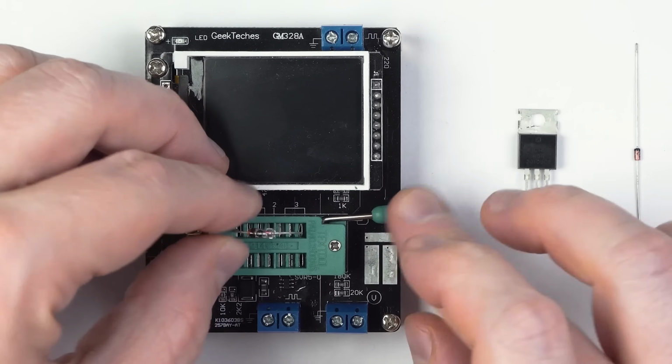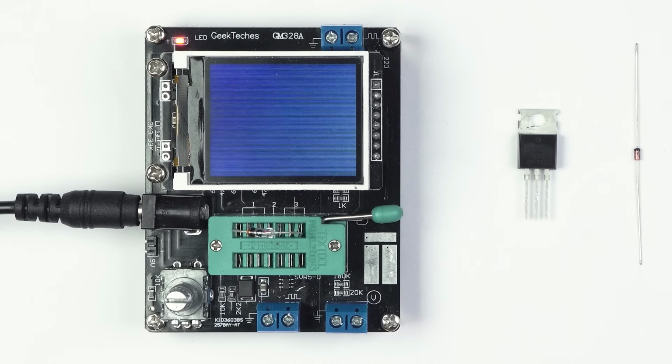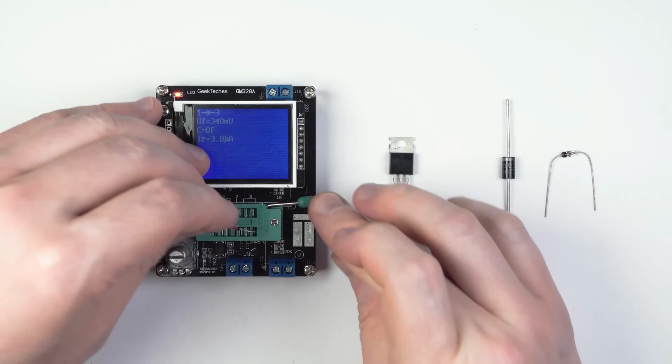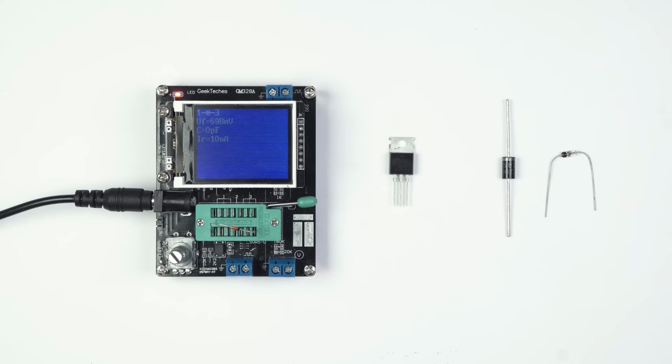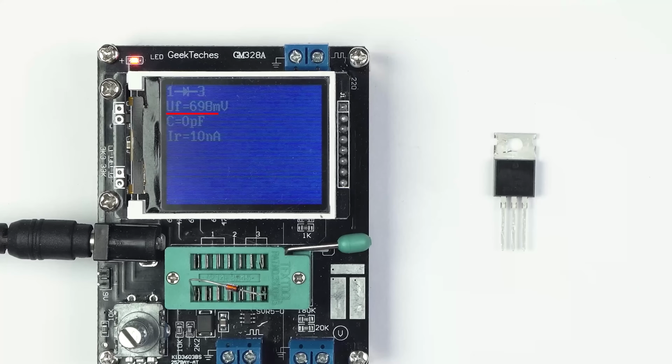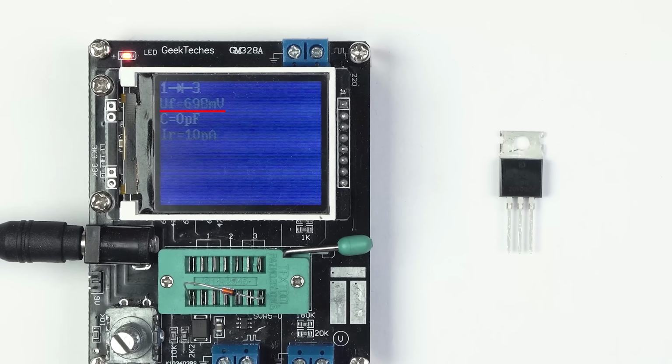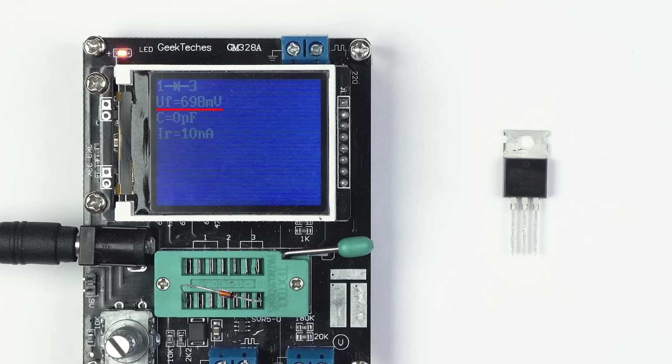Diode, strictly speaking, is not a perfect conductor when forward biased, because, similar to the resistor, it exhibits voltage drop. However, contrary to the resistor, whose drop, as was noted above, depends on a number of factors, the drop across the diode is basically fixed and is usually around 0.6 to 0.7 volts. This particular feature can be used to build a simple step-down circuit.